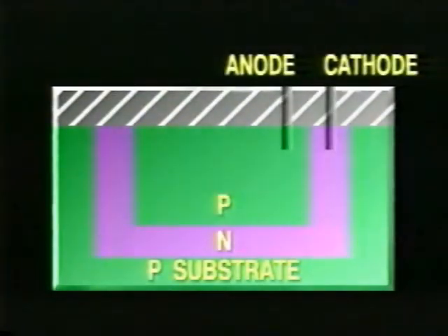Let's see how IC technology depends on basic semiconductor theory. An IC is composed of alternating layers of P and N material, as you can see in this graphic cross-section. By etching into or through the surfaces of 1, 2, or several layers of doped regions, minute components can be made. For example, a diode can be formed by layering first N material and then P material on top of a P-type substrate, which is used as a foundation.